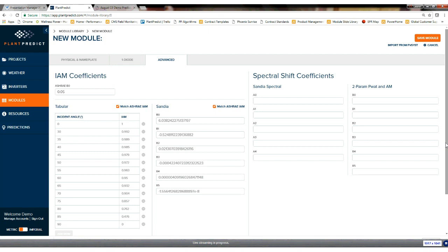Just a little bit more of a note on that. In that study, there were 20 power plants that had operated anywhere up to 5 years. We took the measured energy from their energy meters, compared it to PlantPredict with measured weather input, and found that on average, they were within 0.1% of the PlantPredict output. The standard deviation on that, for the engineers on the call, was about 1.9%. So it was a very good result, and something that I haven't seen done for other software on the market. I haven't seen studies of that magnitude done to evaluate their accuracy.